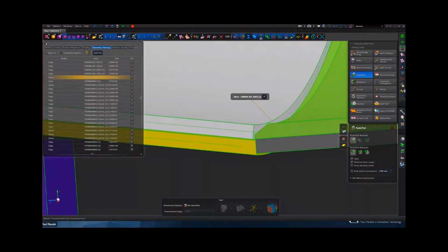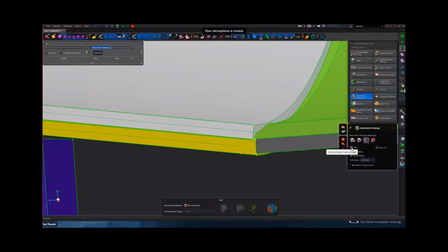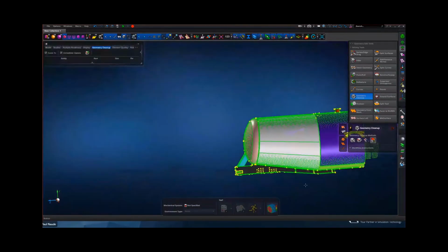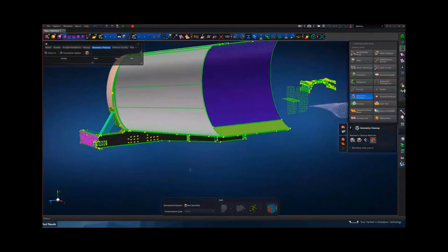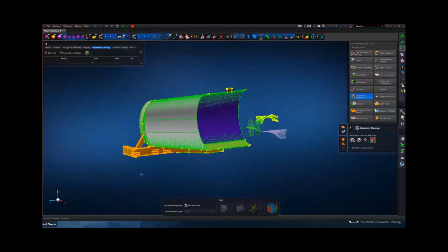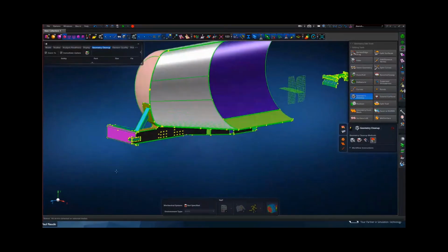Okay, so that is how to find small little defects in your model, as I've shown over here. You can also find gaps and overhangs and small edges. This works on different kinds of technology, geometries. And another one that should actually be the first option in many of your CAD operations is the one to identify if there aren't any defects in your solid. Now, in this case, there aren't any.